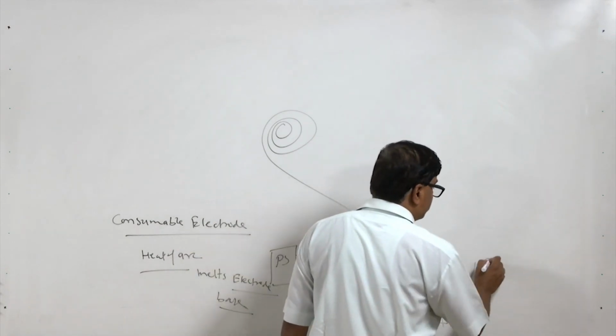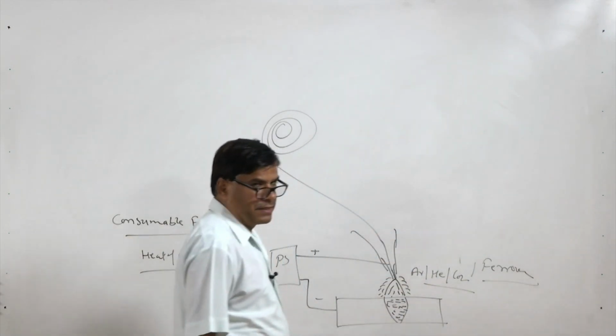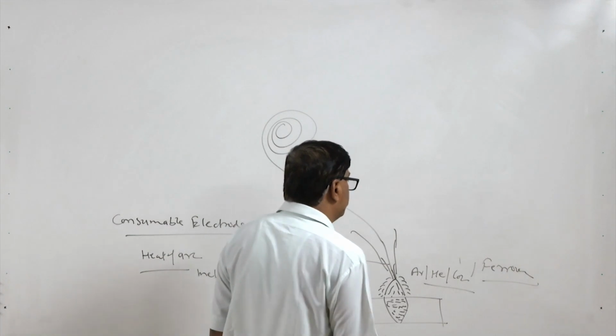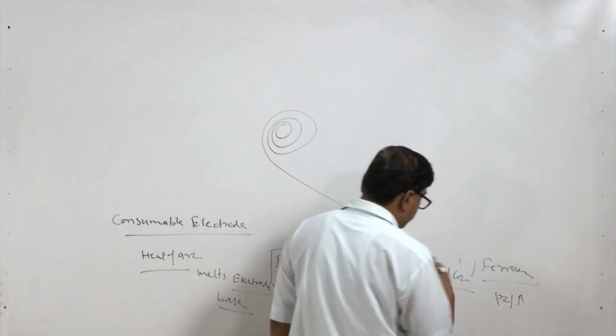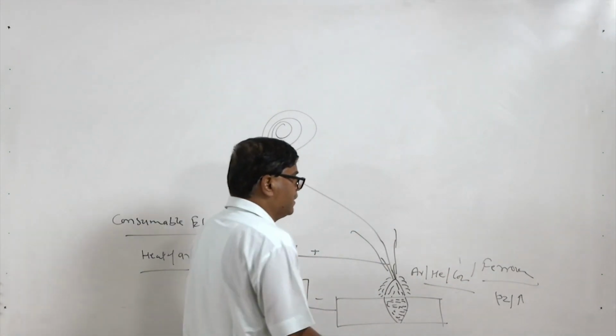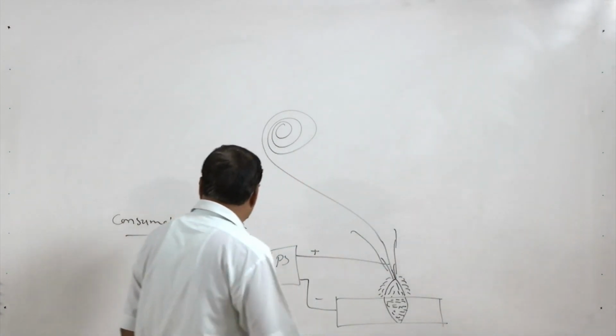CO2 is mainly used with ferrous metals only, not with the others, because it also provides effective cleaning. However, whenever CO2 is used, oxygen concentration in the weld is somewhat more as compared to the case when only helium and argon are used for development of the weld joint.